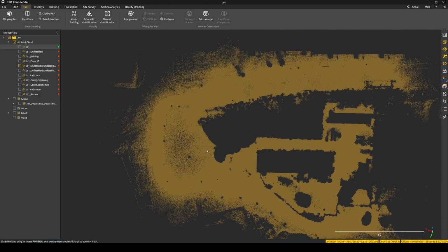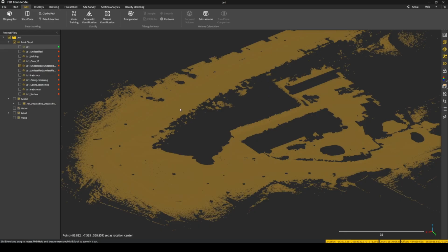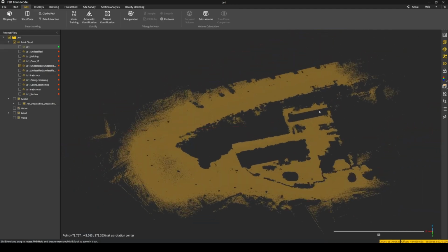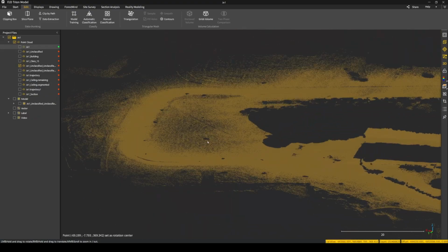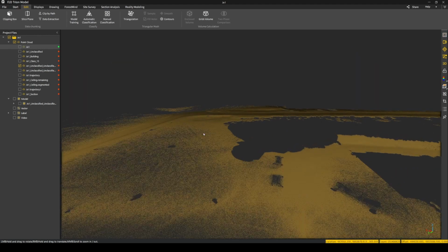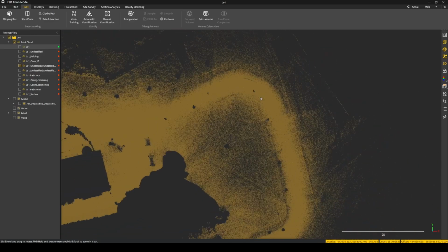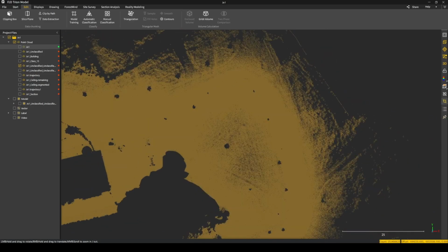And the next step will be to create a mesh that fills all of those holes to get a nice and smoothly infilled digital terrain model. And if you have some noise points and want to clip out some trees, I can show you how I am doing it. So I display the point cloud not in a perspective, but in an isometric way down here. Then I'll hit this top view. And then we can use the clipping tool that is right here.